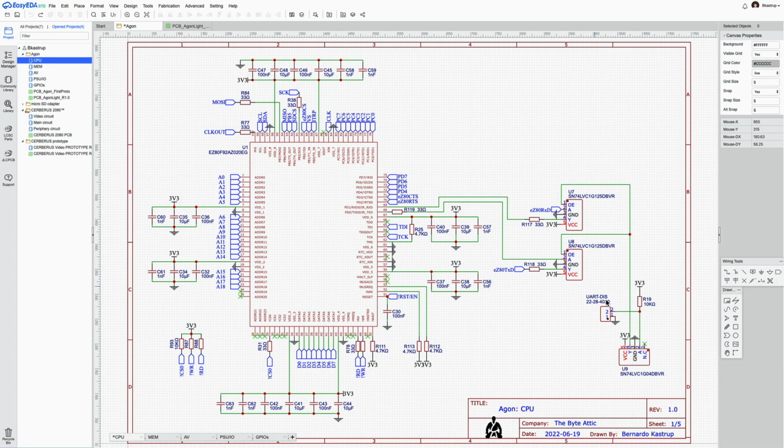All these components that may be unnecessary are dirt cheap, fractions of cents. The only bad thing you get from them is that your layout becomes a little bit more complex. But I decided to bite that bullet and make a more robust board that isn't in any way significantly more expensive because of this extra robustness.